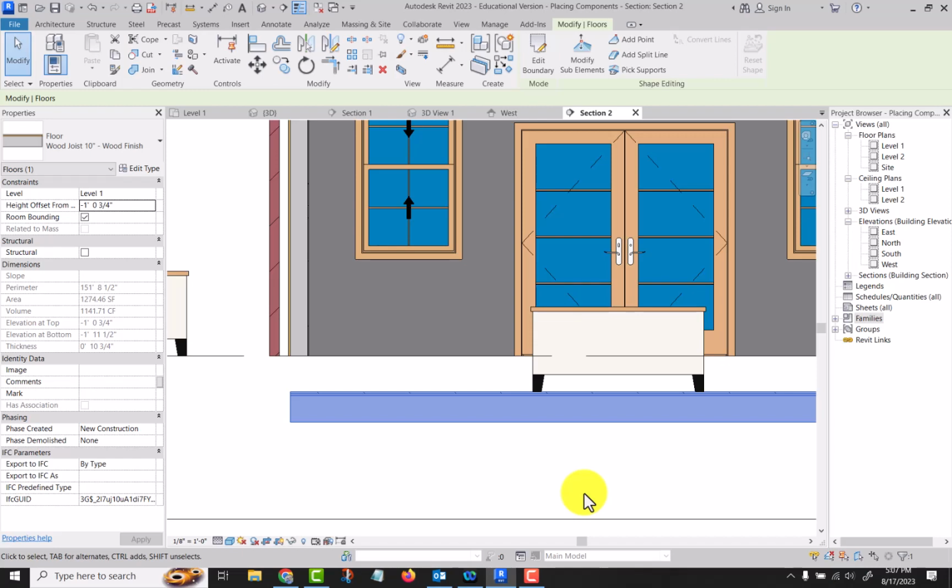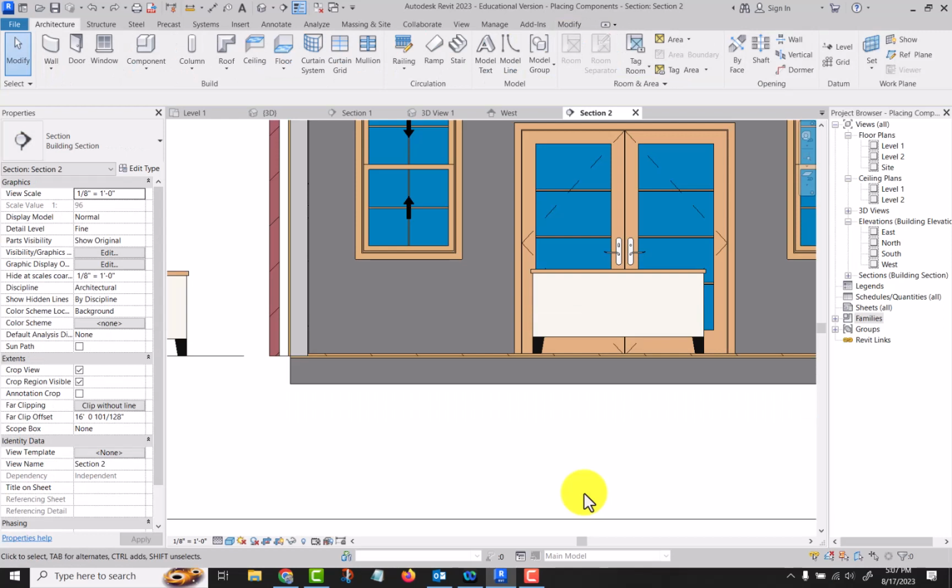Now, one thing that you may see later in some of the projects is if you put furnishings in before you put in a finished floor, then, especially the way that we teach it in the other 2 classes, where you do the finished floor as a separate floor system and it's just on top of your structural floor, any components you put in will be on the subfloor, not on the finished floor. Okay, and sometimes that's okay, like bathtubs go on the subfloor.